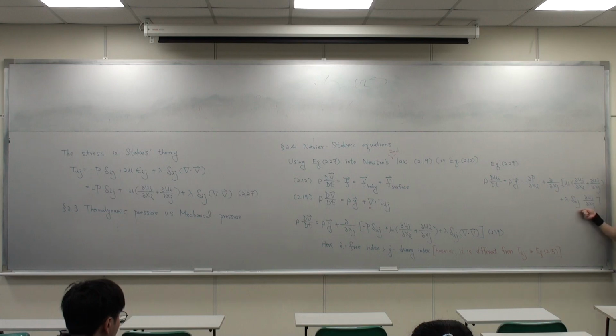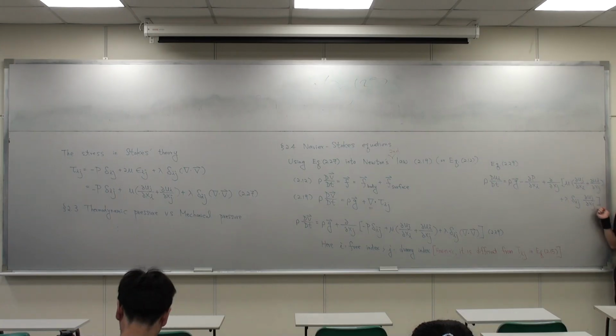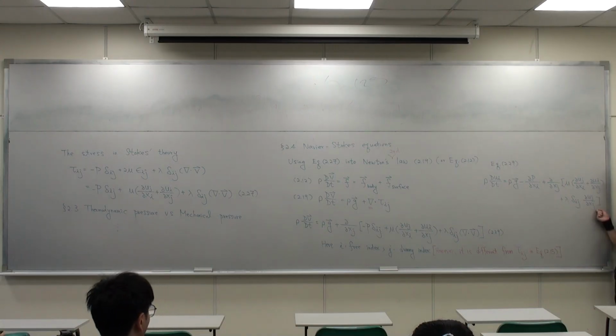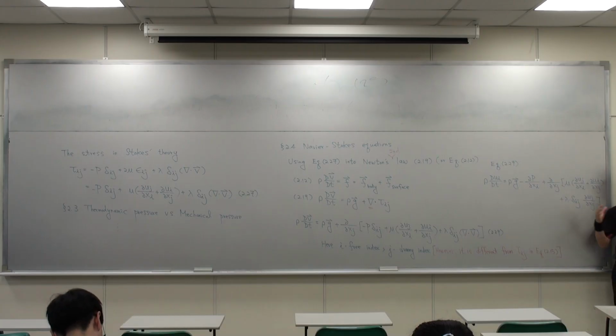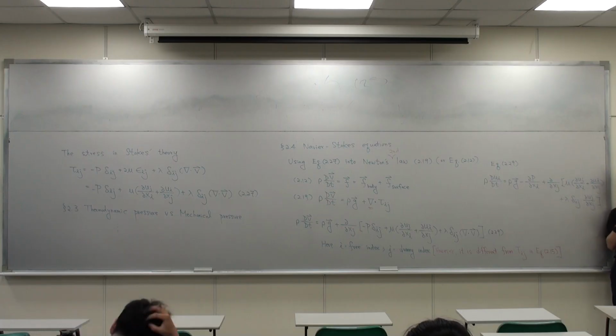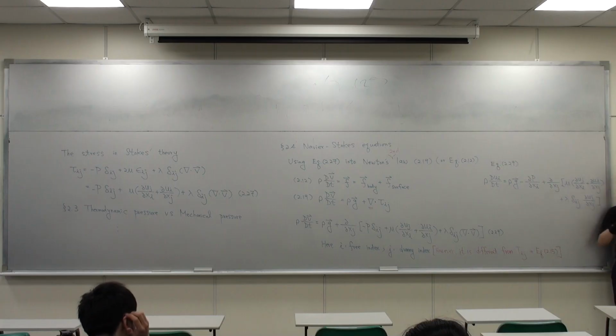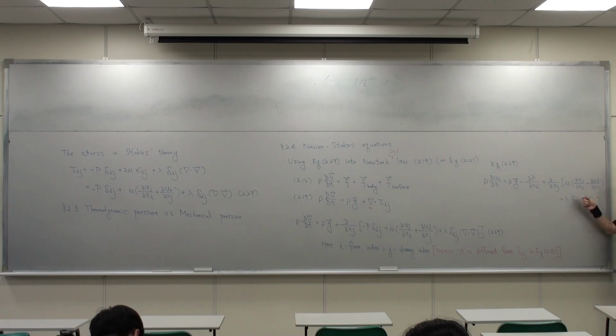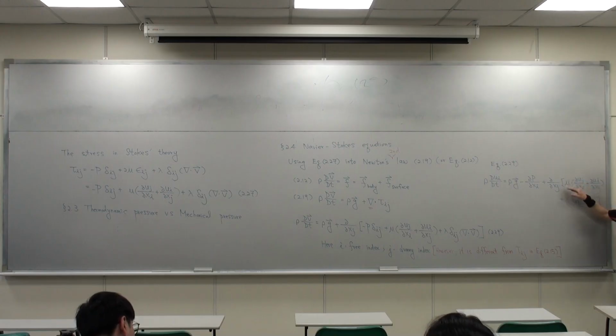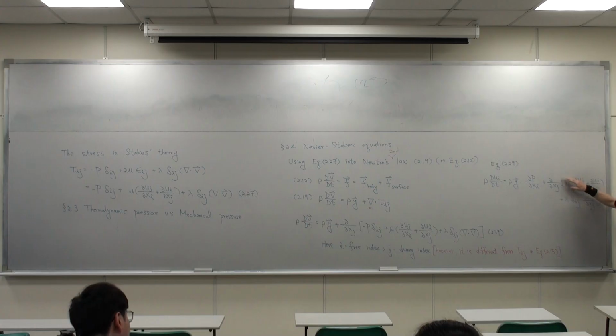Second viscosity, usually we don't consider because the continuity equation is satisfied for most cases. In this class, we don't talk about second viscosity. In case you consider compressible flow at very high speed, for example, if you want to make some kind of space rocket, with a very high speed, then this term should be considered. But in this class, this part we don't consider. So for the shear stress, usually we only consider this.